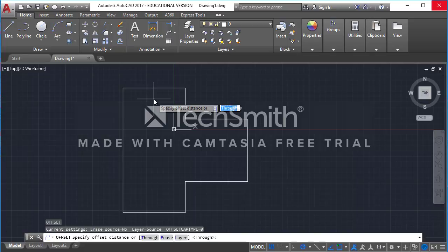Actually, I take that back. I think they're like 5, 6 sometimes. Well, if you're using a 2x4 as your basic, a 2x4 is 3.5 inches, and you have gypboard that's 5/8 of an inch, it comes out to about 5. I think it comes out to exactly 5 1/4 inches. So if you go measure your interior walls, they're probably 5 1/4 inches thick. But for simplicity, we're going to stick with 6 inches, okay? I would probably do all of your exterior walls at 6 inches, and as you start to develop your plans later on down the road, you might do your interior walls as 4 inches, okay?